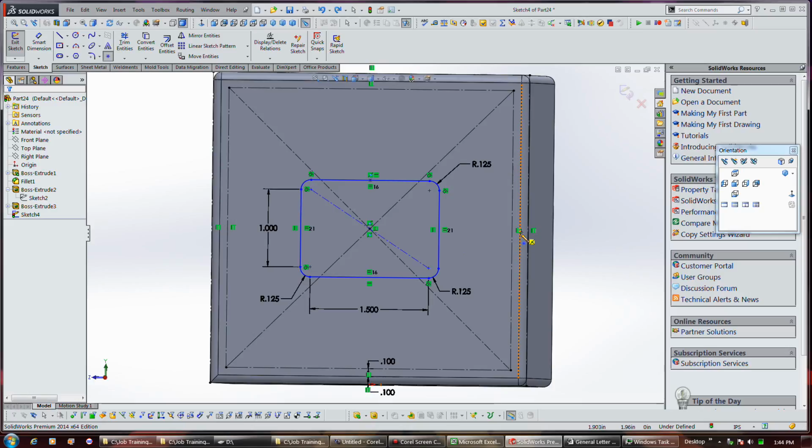Which, like I said, you can do just by clicking a point. But at any rate, once I had that physical point that I could grab, then I could put a coincident relationship between these two points. And I probably just needed to do the find midpoint on this line and then put an actual point on this line, for example.